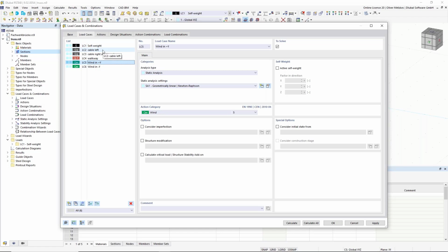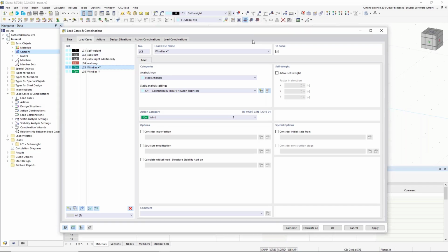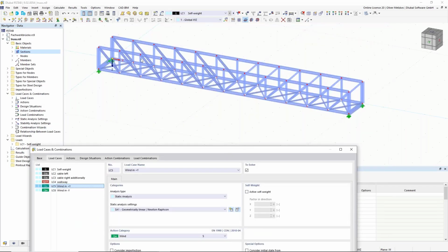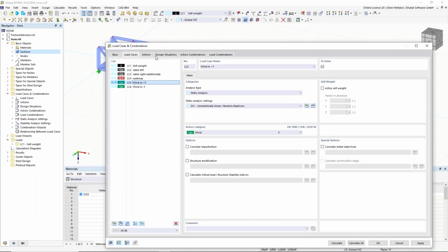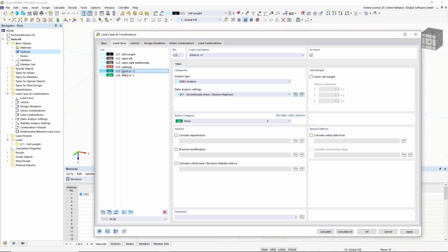So I don't have, for example, temperature loads, to simplify it a bit, but also in my structure, as I have modeled the supports this way, a temperature load would just increase the length, but there would be no internal force from that if I have this uniform temperature load, for example. So I would say for now, that is okay to have this simple structure of load cases.